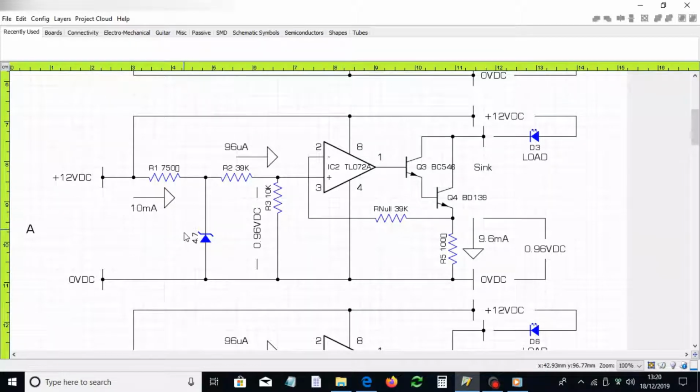So you'd have a whole box load of Zener diodes, and you would go through them, checking them for per degree C change. So you're looking at the thermal change here, and you're looking at the overall performance of the Zener diode, and you can select a Zener diode.